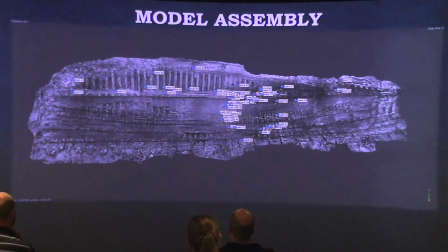Markers proved absolutely necessary to include photography which otherwise could not be aligned to the central reconstruction for unknown reasons. We found that often troublesome images would still easily be used to generate smaller isolated models, which we could then align and merge back into the primary reconstruction with markers. So this method was invaluable to filling all the gaps in the primary reconstruction.